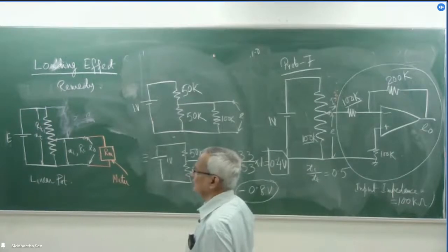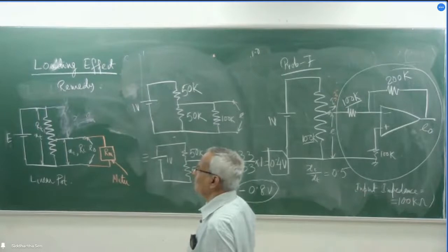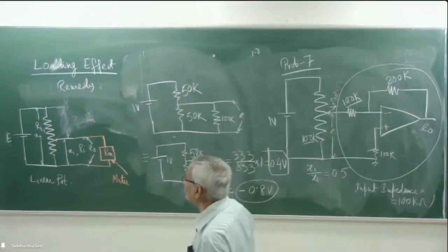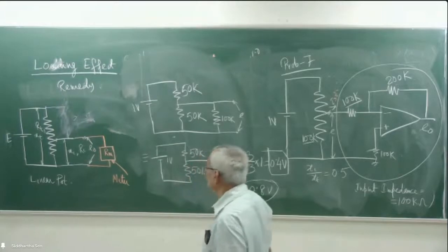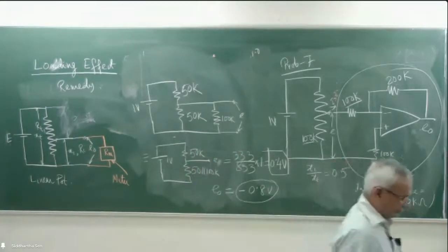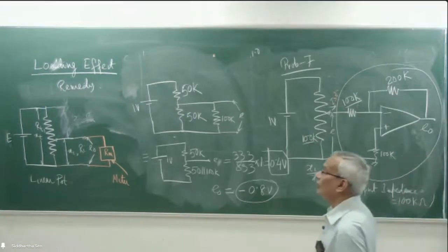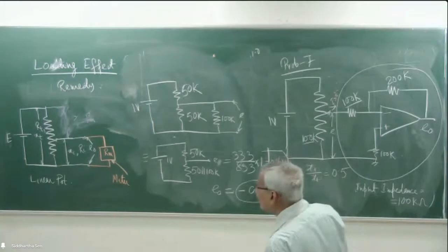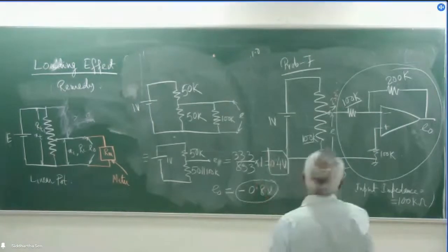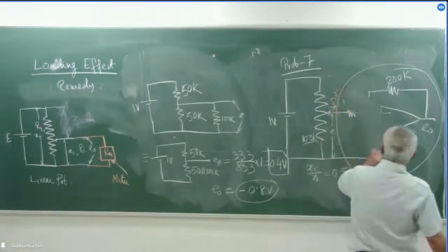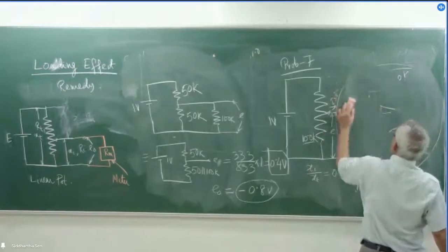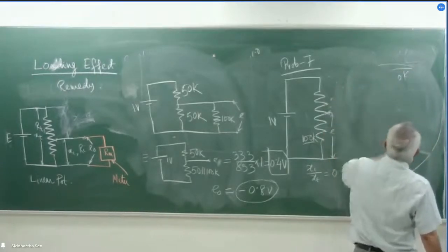Anybody else, can you suggest? So we can use a buffer and then we can amplify it. Yeah. Basically, what is a buffer? A non-inverting amplifier. So we need not use a separate buffer. Actually, it is a non-inverting amplifier.